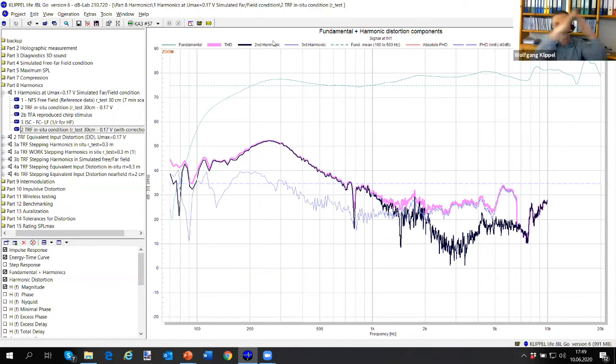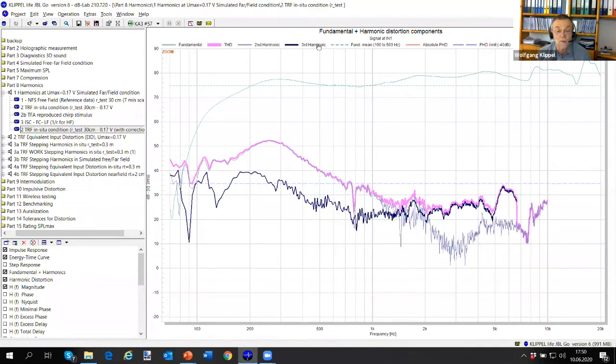We have a voice coil offset in the speaker. That I can directly see from the harmonics. At higher frequencies, the third order is dominant. They are coming from other causes, maybe from modal vibrations or from the L(i). But we are 50 dB down or something like that, so it's negligible.